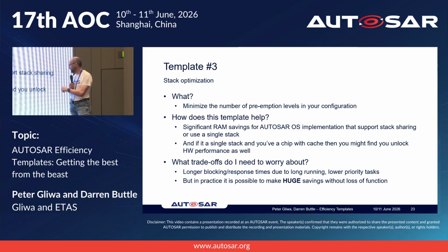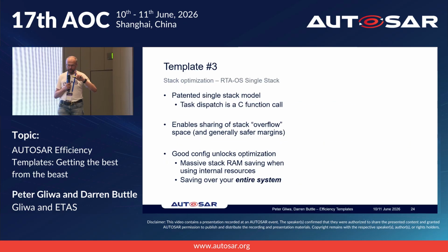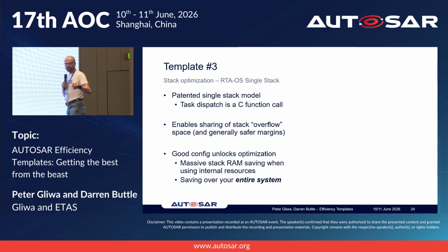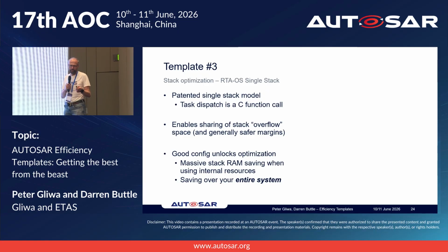And you can have huge amounts of stack saving here. So let's have a look at this. If we do this with RTA, with a single stack model, a task dispatch is a C function call. It doesn't get any cheaper than that.